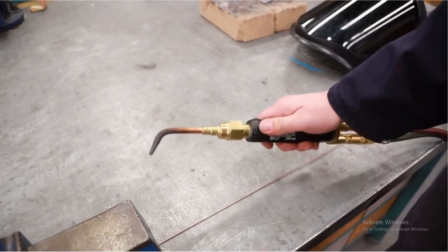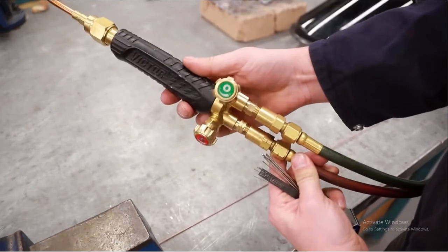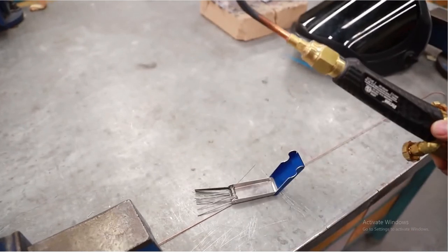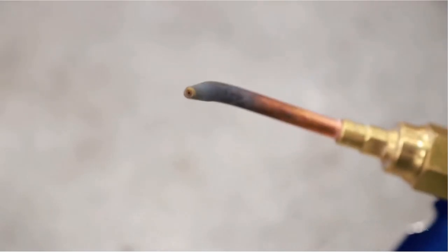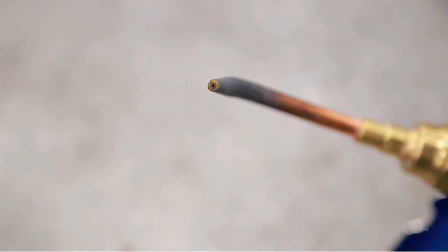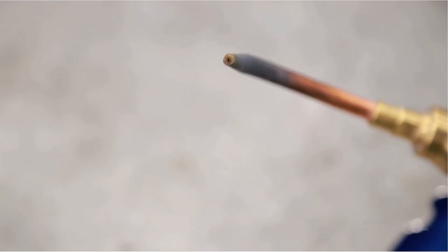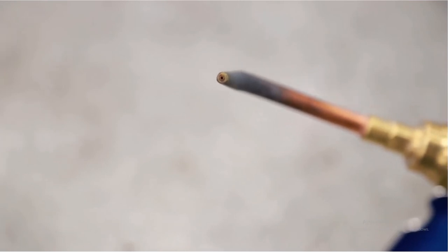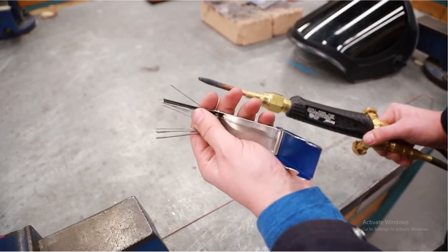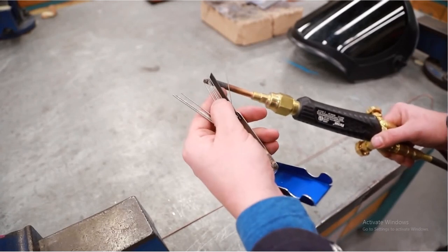So before I get started setting up my tanks, I need to make sure that my torch and everything has been set up correctly. We need to make sure that the tip, there's a tiny little hole here, is clean. It's hard to see. If you do need to clean it, and you can tell once you actually start welding, you can use a tip cleaner. Tip cleaners look something like this. You need to pick the right size for the one that fits in that hole.